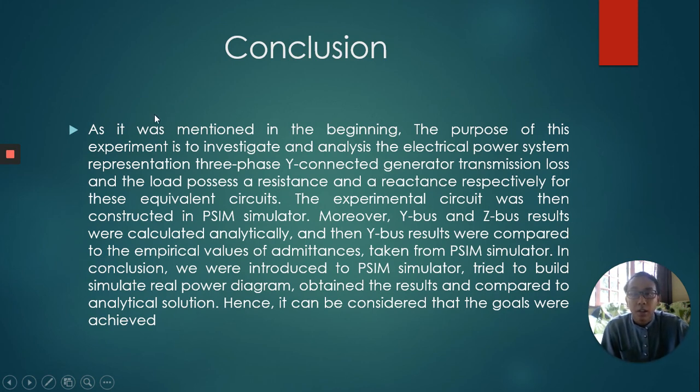And as a conclusion, as I mentioned in the beginning, the purpose of this experiment is to investigate and analyze an electrical power system representing a three-phase Y-connected generator, transmission loss, and load with resistance and reactance respectively for the equivalent circuit. The experimental circuit was then constructed in the PSIM simulator.